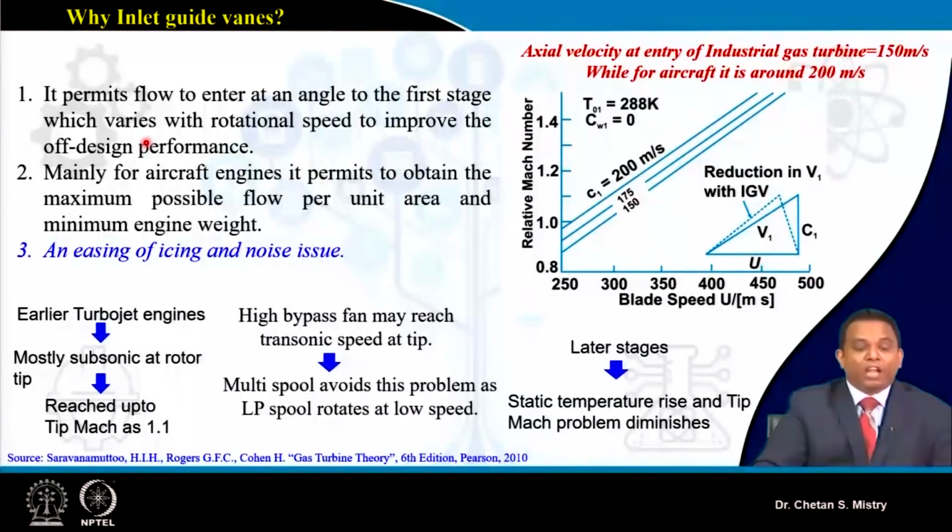It permits the flow to enter at the proper angle for the first stage. That gives the improvement in off design performance. So suppose I am talking about aero engines, these aero engines work under different conditions. We can consider takeoff condition, cruise condition and landing condition. If I am talking about an aero engine for military purpose, we will have subsonic cruise, supersonic cruise, and maneuvers.